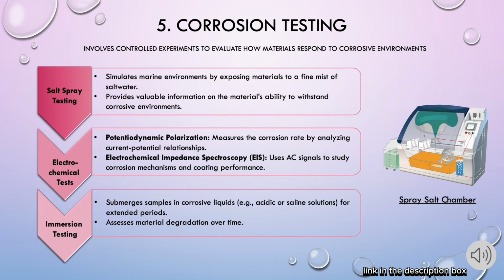And the last one, we will talk about immersion testing, which involves submerging material samples in corrosive liquids for extended periods. This method allows for the assessment of a material's susceptibility to corrosion or degradation over time under specific conditions. These tests can be conducted in various corrosive solutions including saltwater, acidic or alkaline solutions, or chemicals relevant to the